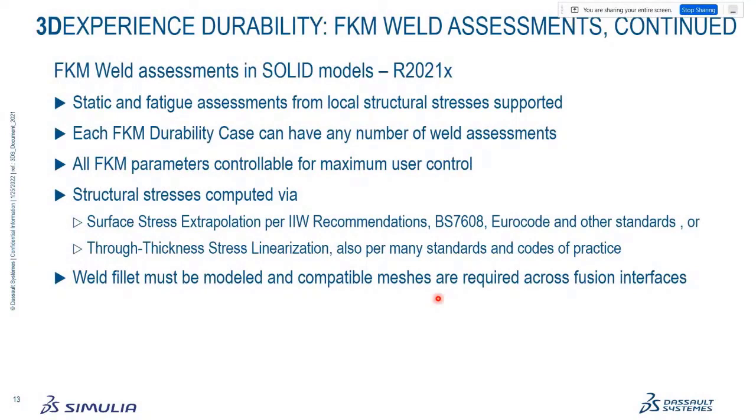Currently, the FKM weld assessments in 3D Experience platform only deal with solid models. We still have to get to working with shell models, for example. We also only do weld assessments today. We don't do base metal assessments yet either. Okay.